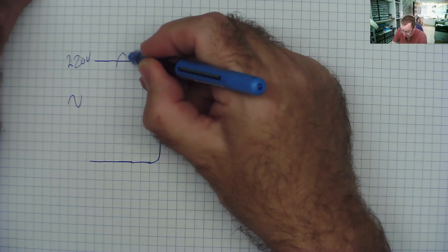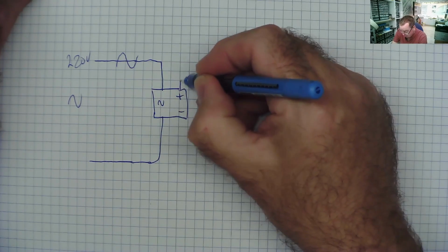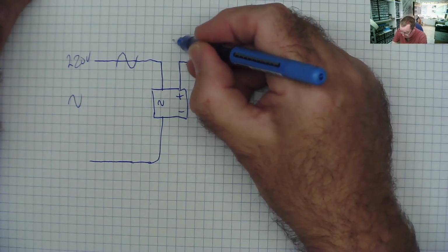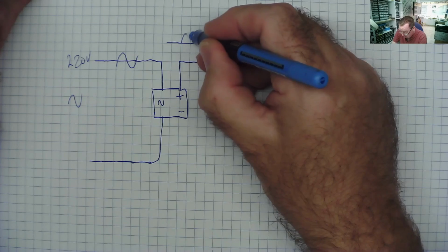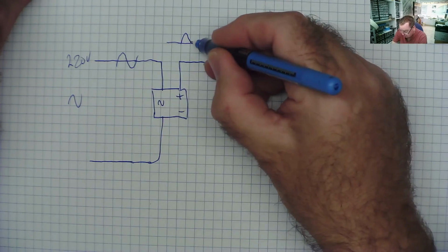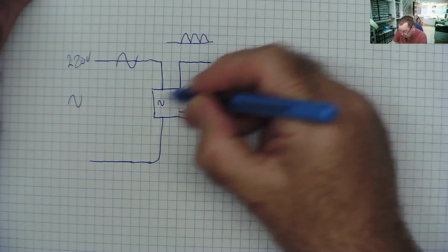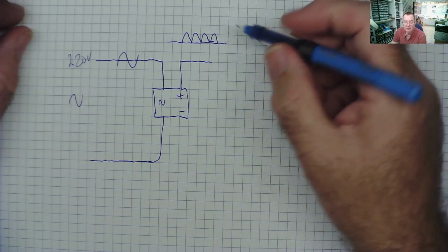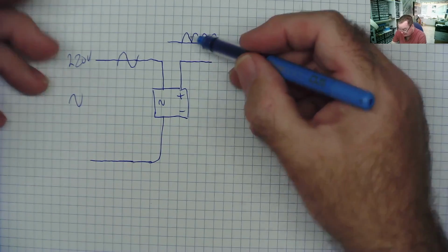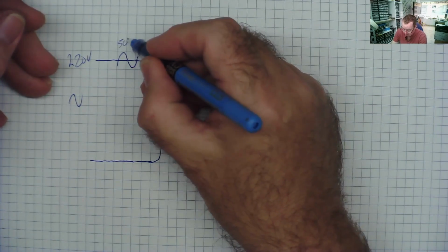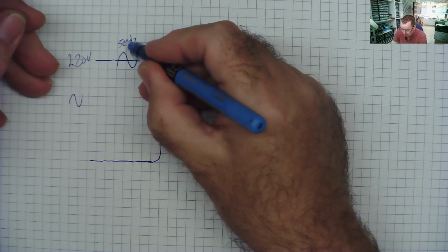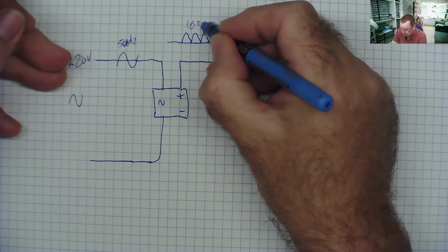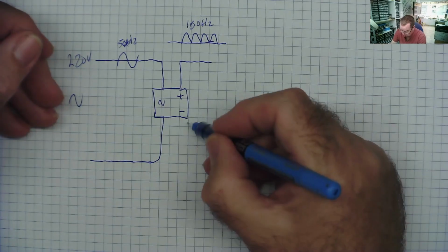So this, as I drew before, is an AC signal, and coming out, we don't have any smoothing capacitor on here. So what we actually have, this is your 0 volts. We have a half cycle, and then the other half cycle is turned upside down. Half cycle, other one turned upside down. So we get this pulsed DC, which is actually at twice the frequency of that. So if this is 50 hertz, because we're turning half the cycle upside down, it's no longer a sine wave, and it's running at 100 hertz. Okay, that's what the circuit does.